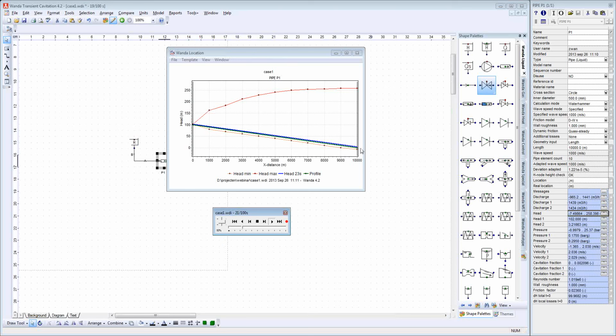See, nothing is happening. The valve is closing, but it's not doing anything yet. And now, as you can see, the pressure starts to build up. The pressure wave going into the pipe, which reflects, comes back. The valve is closed, and you see it gives cavitation along the line. Now since I only have 10 points along the line, this is a very rough calculation.